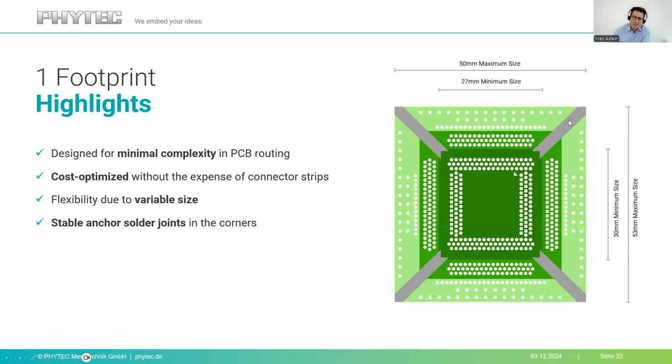And these anchor joints are on the carrier footprint. If the system on module has a size limited to, for example, this much, as I'm showing here with the cursor, then there will be a solder connection on the edge of the module, and it will connect to this landing strip, as you could call it, by soldering on.